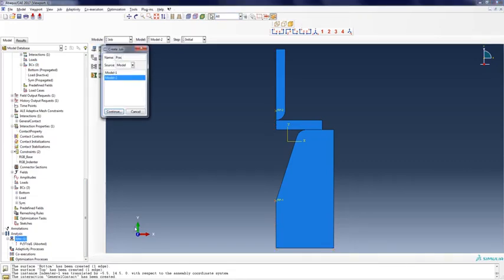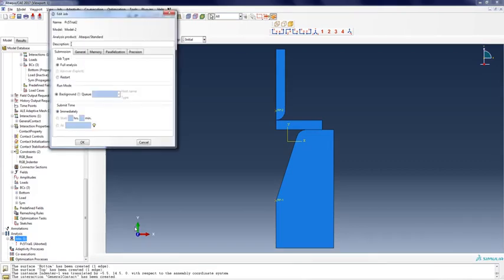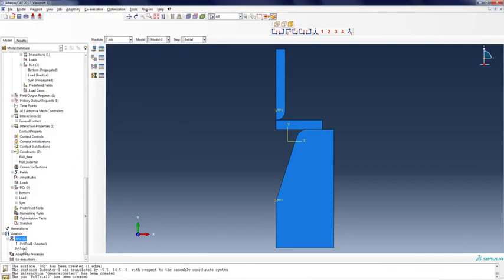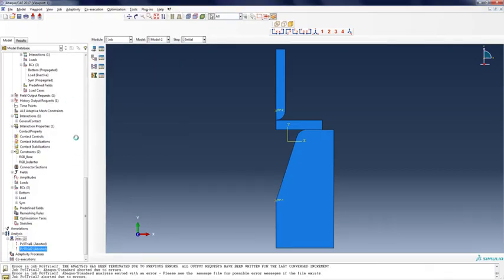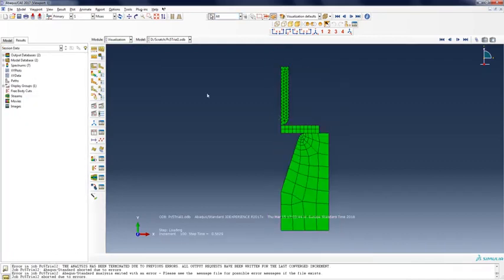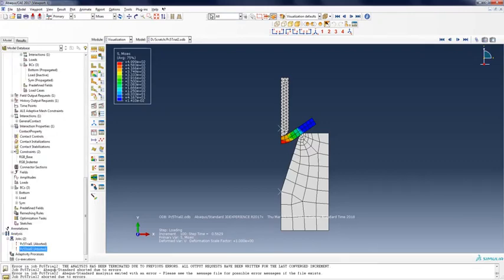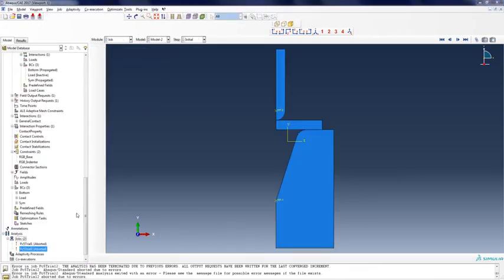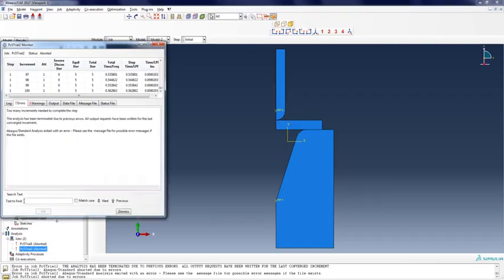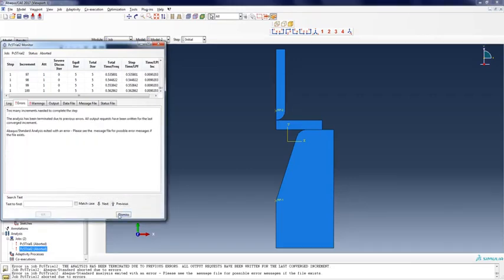Track PC5 trial 2. And think about it again. Okay, this time is much better. We run into 0.56 and increment 100. So let's have a look at the error message, because I suspect that this is because we run out of increments. Yes, too many increments needed.